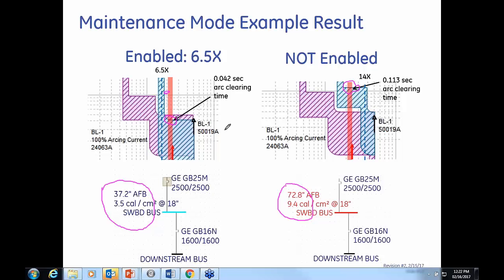2,500 amps, is that good enough? Well, that's where engineering judgment comes in, and what's the accuracy of my utility data fed into this modeling? What's the accuracy of my cable lengths, which also contribute impedance? What's the accuracy of my transformer data? If the combination of all those variables means in real life, because the real life data is a little different